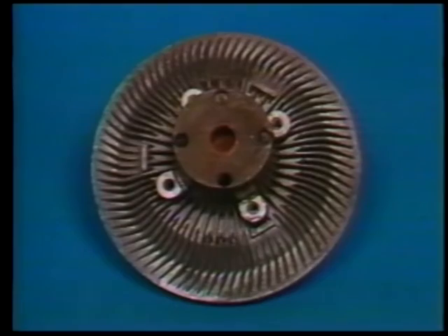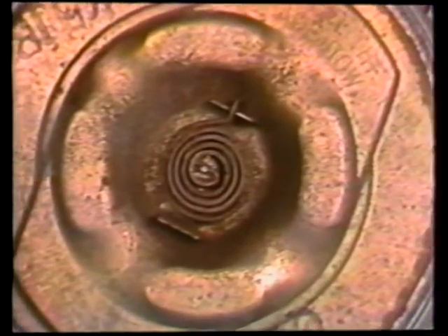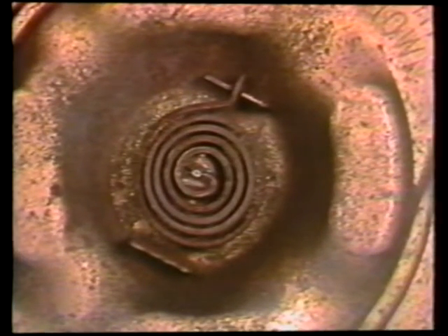When a vehicle is moving, there's plenty of airflow through the radiator to remove heat. When a vehicle is not moving, the radiator fan must draw a sufficient volume of air through the radiator to provide cooling. Many vehicles use a clutch-type coolant fan. These units use a silicone fluid clutch controlled by a bimetallic thermostatic spring. This clutch allows the fan to slip when the engine's cold or when down the road driving supplies enough air to control coolant temperature. This reduces engine drag, increasing fuel mileage when the fan is not needed.